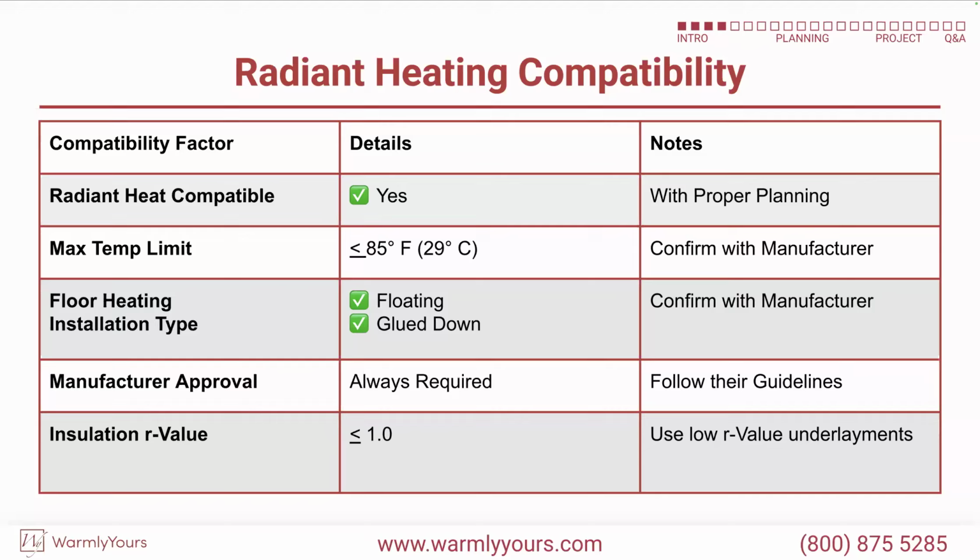The insulation value of the flooring itself, right, Scott? Mhm. This is important. We want the heat to come up and rise and keep you warm in your room, so we don't want your flooring to have a high R value. One thing you're going to find with LVT, the old fashioned 12-inch square vinyl tiles, is that they don't have a backing on them. They're usually adhesive; you peel the stuff off and stick it down. There's no pad in between.